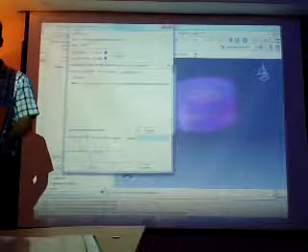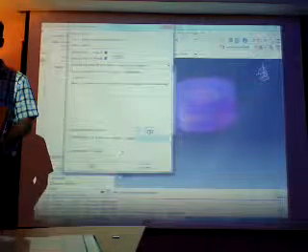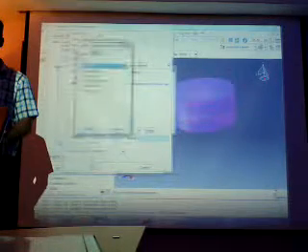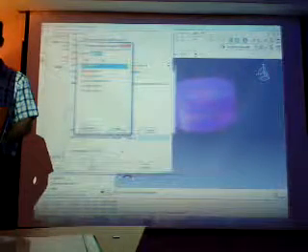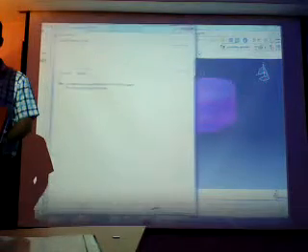For contact interaction properties, you need to create contact interaction properties. We are going to create contact interaction property 1, continue. We have another window here. In mechanical, our contact is just mechanical here. You can see here different kinds of mechanical interactions with a tangential behavior.